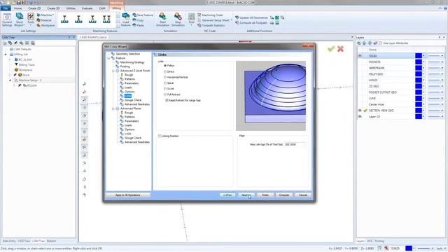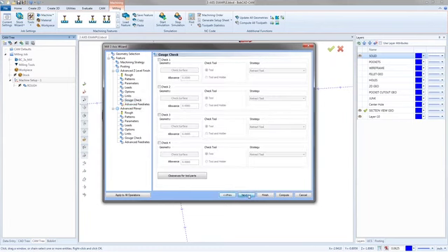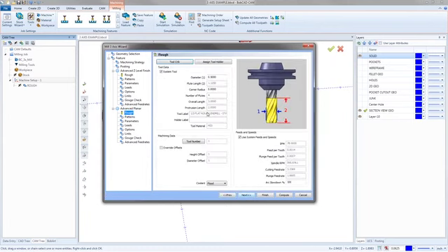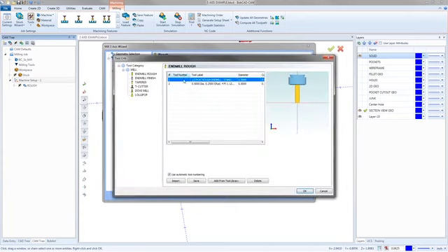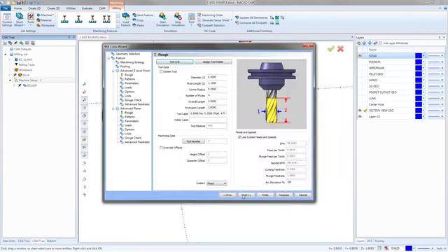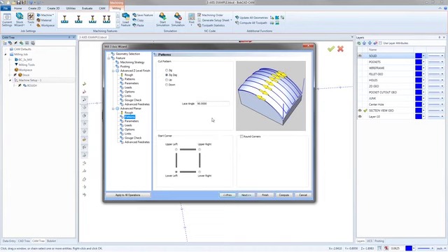So links, not changing anything there. There's that gouge check again and the advanced feed rates. Right here, I'm going to go ahead and use the same tool. So I'm just going to jump up to the tool crib, pick my 1/2-inch ball mill, then hit OK. Next, right here, we have our patterns. Really not too much to this one. It's a planar toolpath, so it's just going to go back and forth, up and over, whatever it's got to cut. It's a very easy cleanup toolpath.